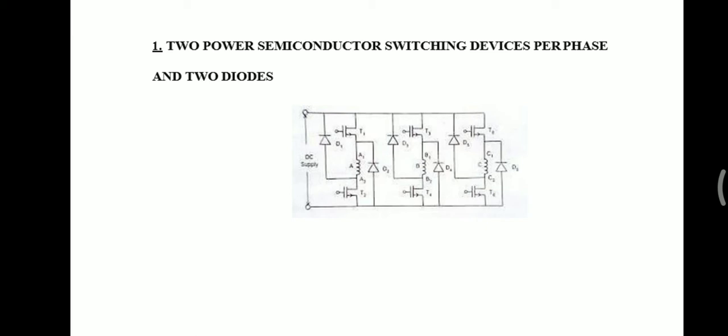the mains. Similarly, phase windings B and C are also switched on to the supply and switched off from the supply in a cyclic manner. This circuit requires two power switching devices and two diodes for each phase winding. For high speed operation, when required, the stored energy can be fed back to the mains within the available period.